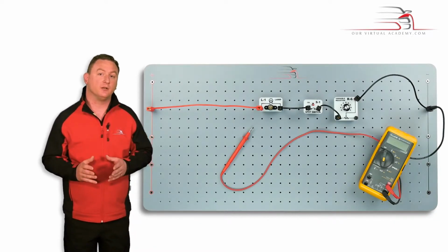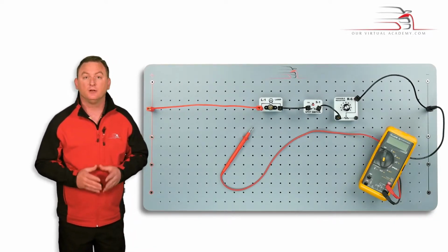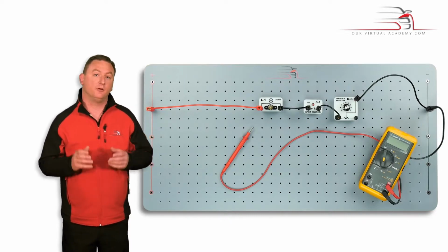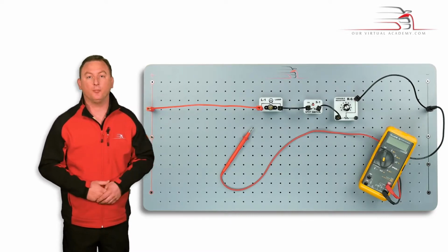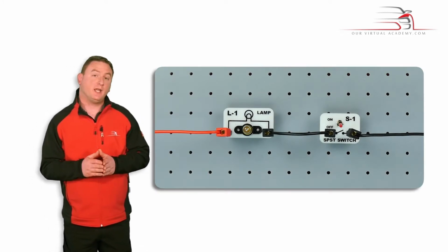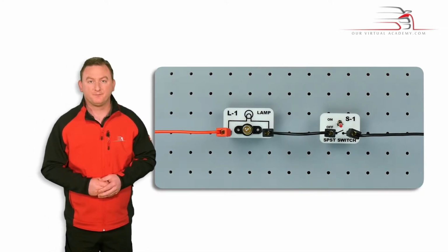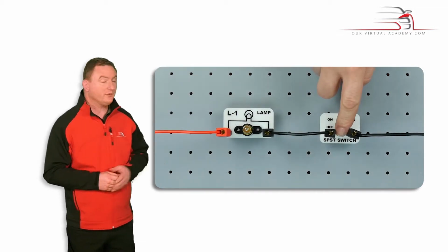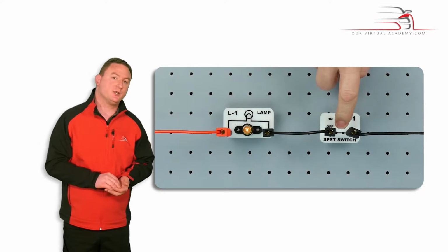The solution is electronic control via PWM. It's fast, cheap, fully controllable and compact. So imagine having control of the switch and switching it on and off at a set rate. So we'll do this at, say, once a second, i.e. 1 second off and 1 second on.